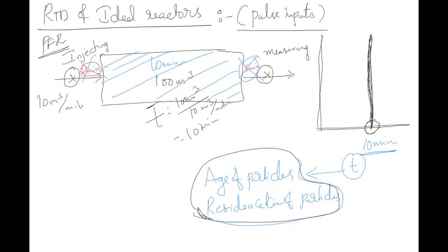We are not saying these 2 minutes or 5 minutes are residence time, because they are not inside the reactor. They are outside the reactor. Outside the reactor, whatever time is spent doesn't matter to me, because that is not useful for the reaction. So space time is different. I'll explain in later classes the difference between residence time and space time, but don't get confused here. That will come in gas phase reactions.